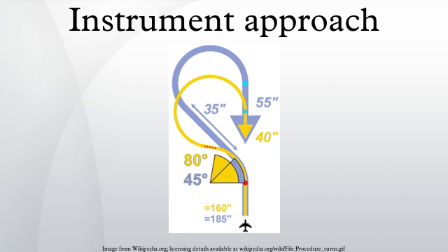An aircraft must not descend below the MDA until visual reference is obtained, and from which the aircraft can land while performing normal maneuvers. This differs slightly from a DH/DA in that, while the missed approach procedure must be initiated at or prior to the DH/DA, because of its vertical momentum during a precision approach, an aircraft may end up descending slightly below the DH/DA during the course of the missed approach.